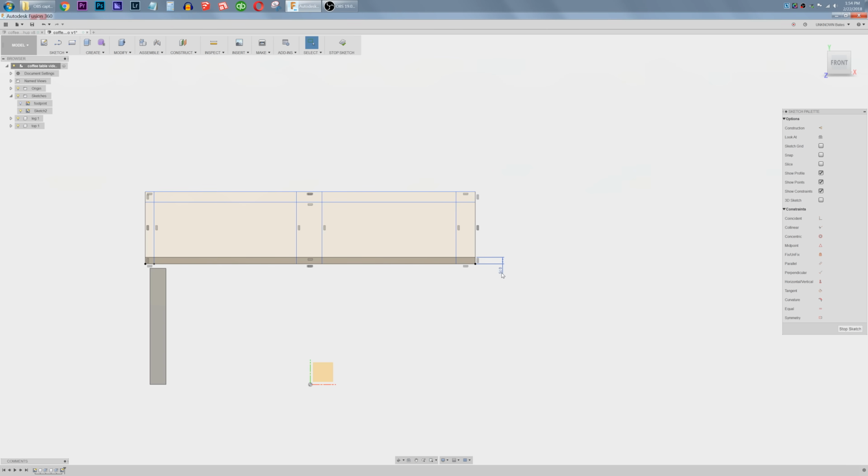Again, I could set a parameter here to material thickness and I would not have to worry about things lining up, but I'll cover that in another video. In this case, I just want to show you how you can link within sketches. So this is my material thickness, but every single one of these is the same thickness as well. So I can go D for dimension from here to here, and instead of typing in a dimension, I can hover my mouse over here and it says D13. I can either type in D13 or I can just click on it and it'll type for me, D13. I'm actually going to select that and copy it really quick.